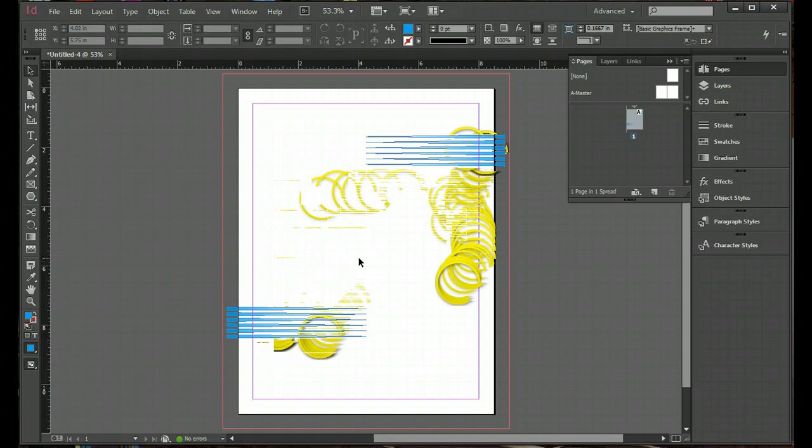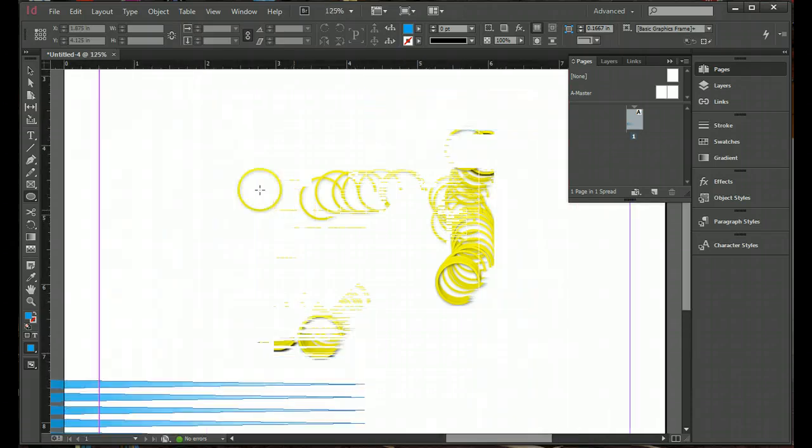Next, we're going to try something very quickly using a different shape tool. Okay, this time, assuming that you've left everything in place, and that's perfectly fine because I want to see it, go ahead, click and hold the polygon tool, and this time go to the ellipse tool. Now I'm going to have to zoom in here a little bit, and the problem with the ellipse tool is that it gives you just that. It gives you ovals. Now if you want ovals, that's fine, and in Unit D I believe you're using ovals. But right here, if I hit the Shift key and drag, I get this perfect little circle.